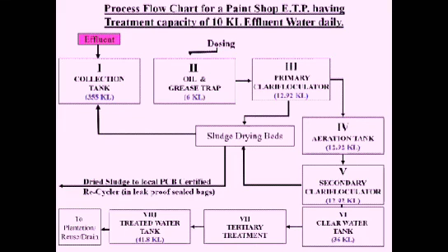But if we want to make the water potable, then we have to have the fourth stage of water treatment, which is tertiary treatment, which consists of various wire mesh or porous big filters, which may be ranging from 200 microns to maybe 10 microns stage-wise.